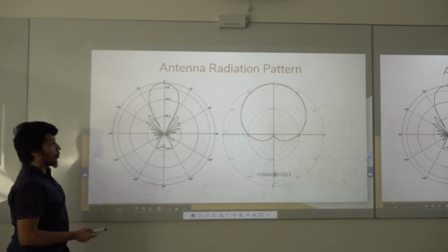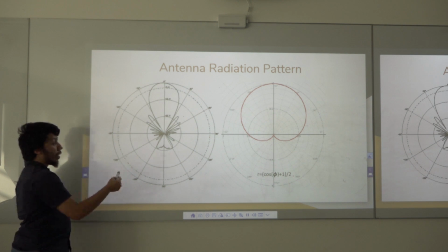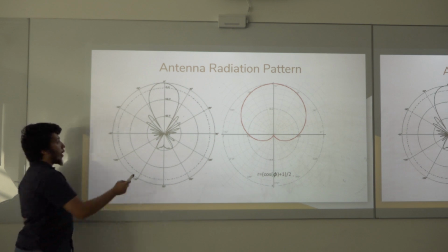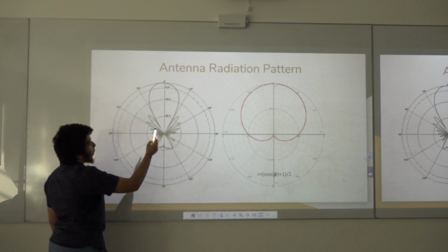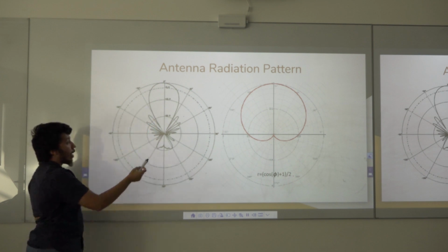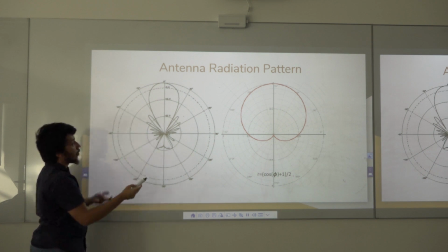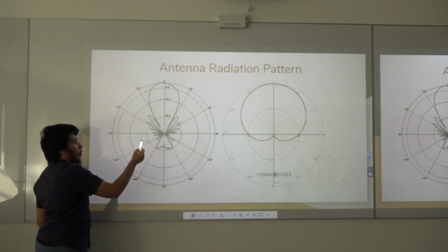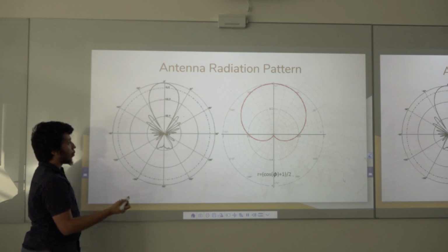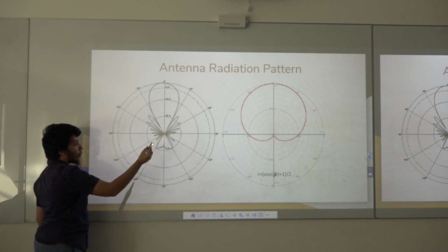The antenna radiation pattern is important to note for these experiments. The Yagi antenna, and whatever directional antenna we imagine to use for this system, has this general form where we have a peak at 0 where it's pointing directly at the source and a strength that's less than unity at every other point. We aim to have this behavior so that when we do our comparison, we know that the motor has to rotate, and we don't really care that there are lobes around the side,